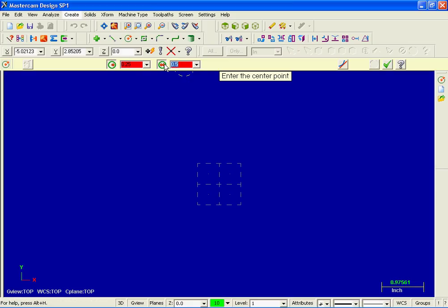and I'm also going to click on the diameter icon. As you can see, they've turned red. I've locked these values in. So here's my first prompt, enter the center point. Now I'm going to move on down to the center of the grid. This first circle, the center point is X0, Y0, and on the screen is a visual cue that I'm going to snap to the origin, X0, Y0. So I'm going to pick it,